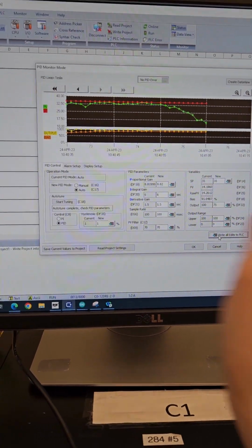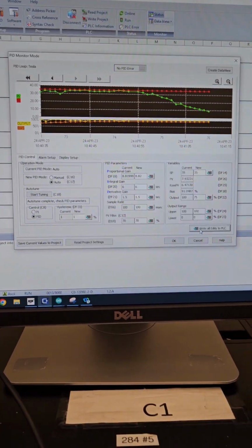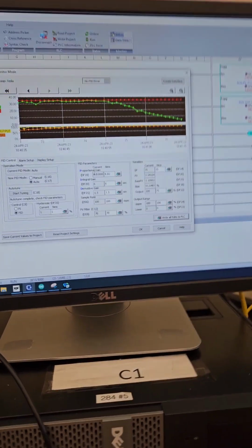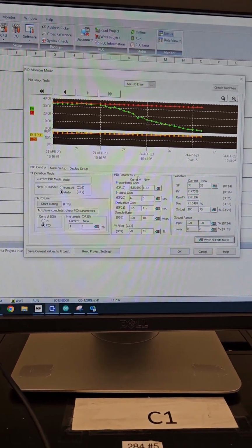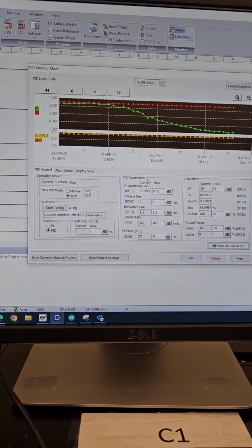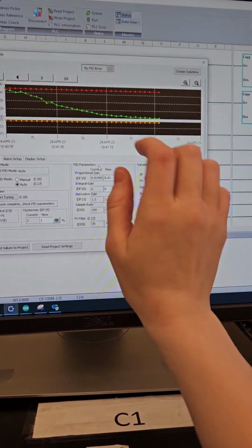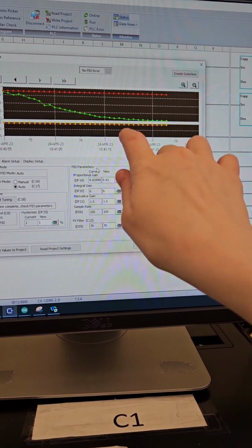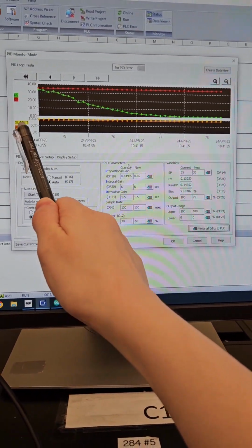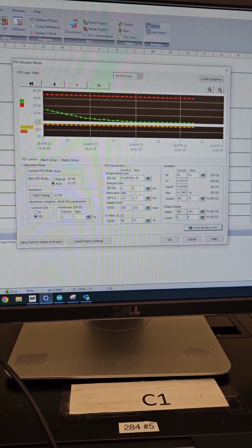So how we found our proportional, integral, and derivative gains were, first the proportional gain. I ended up with a KU of 15, because when I had it on 15, it wasn't hitting the upper or lower limits for the output and bias.